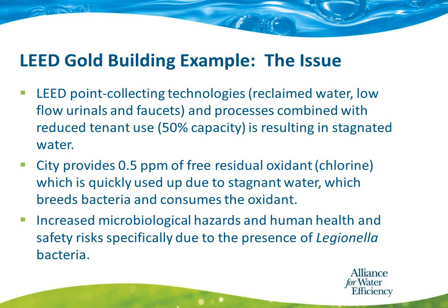Now, the city was providing 0.5 parts per million free residual oxidant as chlorine, but it was quickly consumed due to the stagnant water. And of course, in that situation, we know that bacteria and other microorganisms could proliferate because there wasn't enough disinfectant. And this resulted in increased microbiological hazards and human health and safety risks, specifically due to the presence of Legionella bacteria.